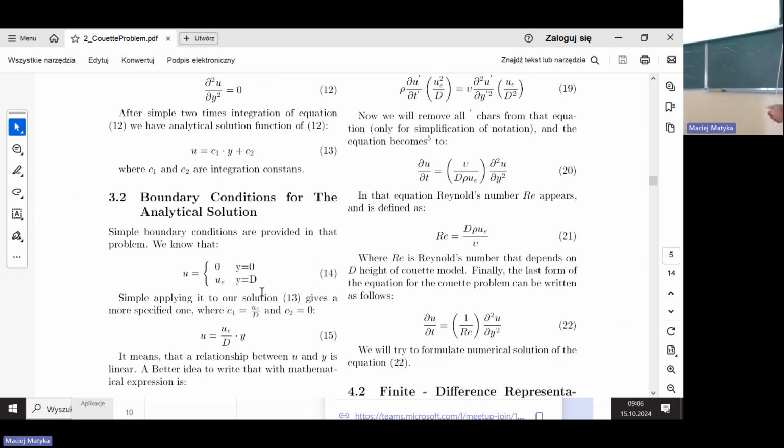So let's say it's here, the smaller one, okay? Which is basically like this size. Put it into a wind tunnel that is of this size as well, also scaled, and just put a viscosity of the fluid which is 10 times higher. So 10 times higher viscosity in the smaller system is the same as the original viscosity in the large one. Then you can perform the experiment here and do the same optimization.